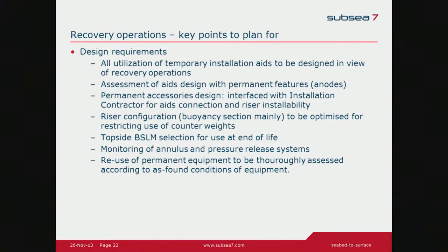Monitoring equipment onto the pipe to know what is going on in the annulus, especially to avoid burst, for example. And reuse of permanent equipment needs to be thoroughly assessed if we need to do it 20 years after its first installation, according to as-found condition or original design.